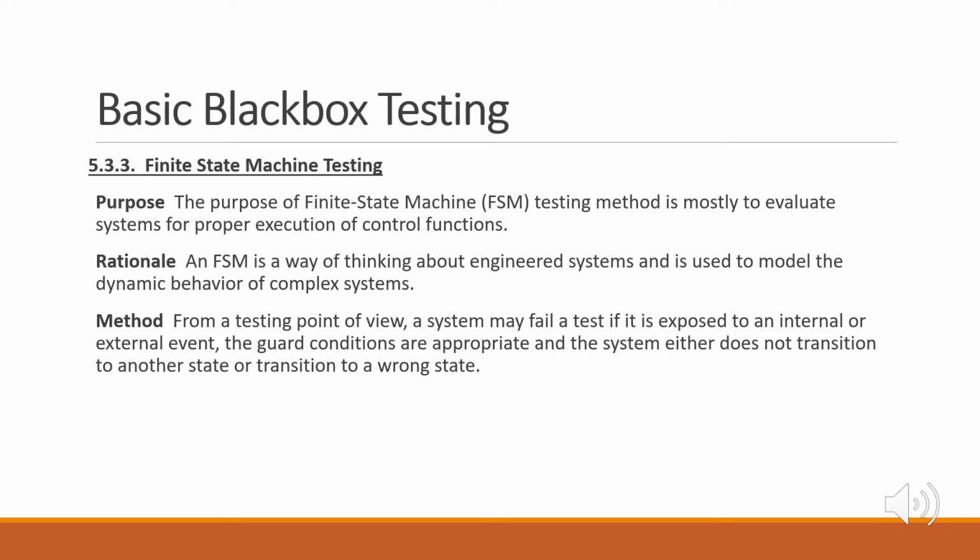Typical FSM testing strategies are as such: test for fault action, test for guard condition fault, test for an unspecified event or missing transition, test for illegal event failure, test for unintended event failure, test for state fault, test for next state fault, test for extra transition.